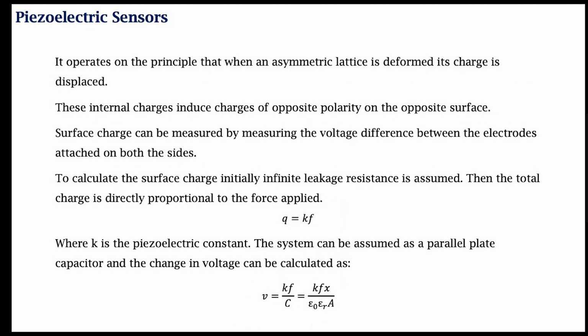It operates on the principle that when you subject an asymmetric lattice to a force or a stress or a strain, there is a charge displacement that happens, leading to development of an electric field. So it induces charges of opposite polarity on two surfaces. This can be measured by measuring the voltage difference between the two electrodes on the two sides.